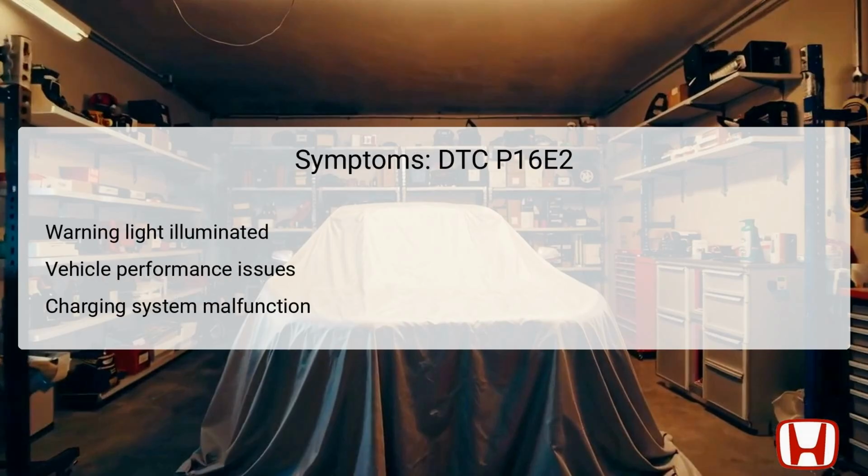The symptoms accompanying DTC P16E2 can manifest in several ways. One primary indication is the illumination of the warning light on the vehicle's dashboard, signaling a communication error. Drivers may also experience various vehicle performance issues, which may include reduced power during acceleration or erratic engine behavior caused by the PCM not receiving accurate engine data.